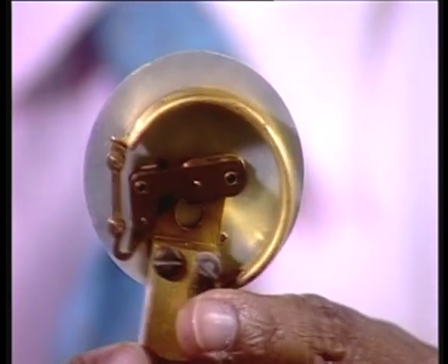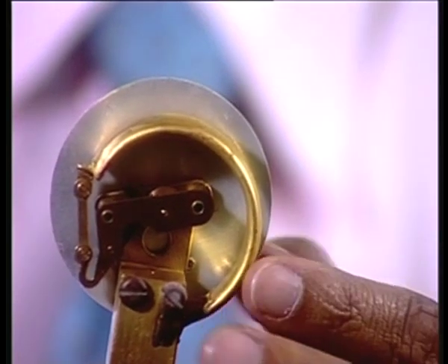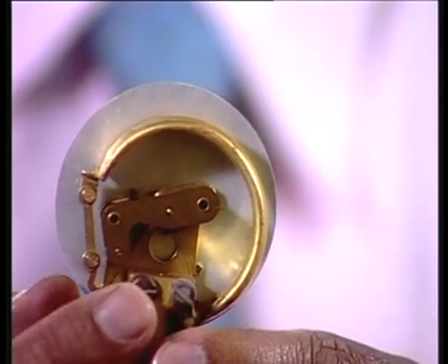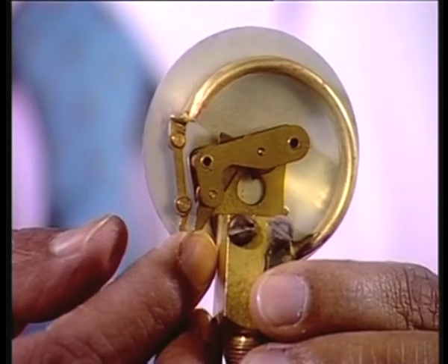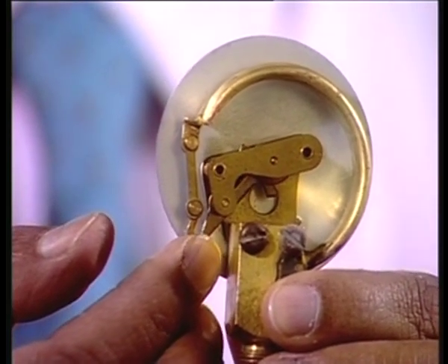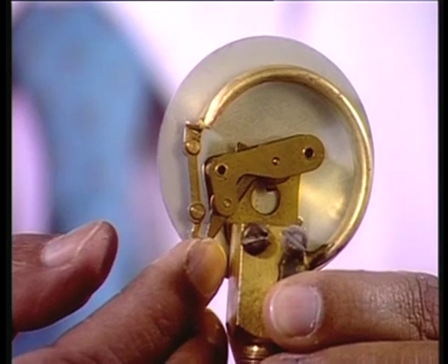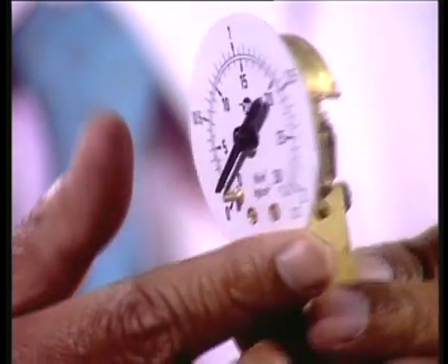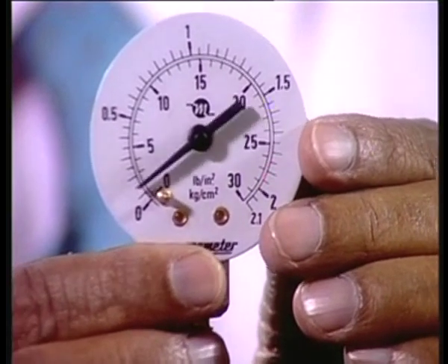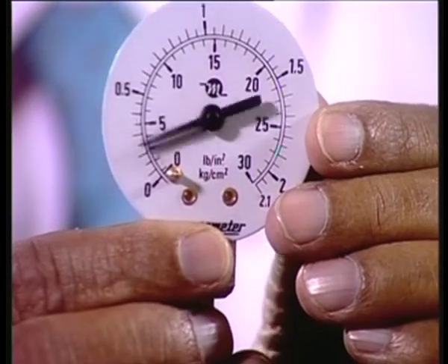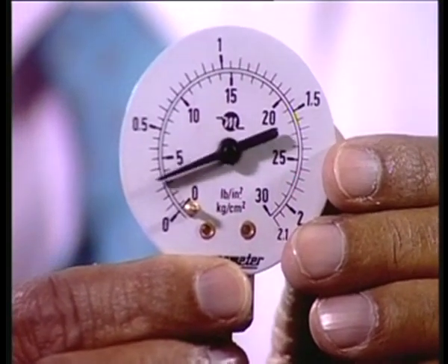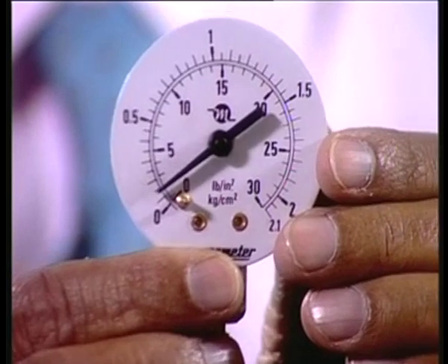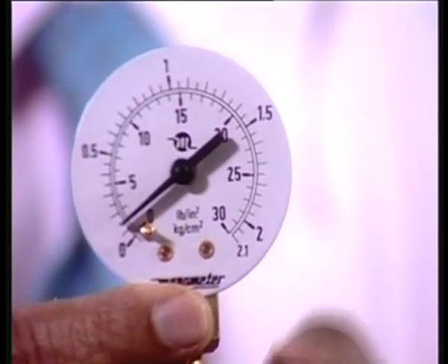You see that if I move this, because this tip will move outside, is it not? So what will happen when the pressure increases? It will move this way. You see the sector will move. There is a hairspring, the sector will move, and if the pressure increases, again it is coming back to the original position. Now you see here, because now it is at atmospheric pressure, there will be no movement.